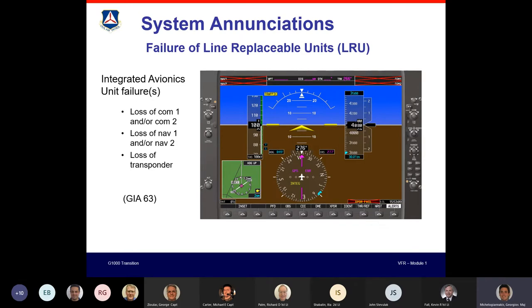Now, there's some training videos about it. If your AHRS is going to fail, the G1000 doesn't necessarily know that right away. So there is a period of time where you might get weird indications. So that's why we tell you to cross-check. We use standby instruments every now and then, especially if you suspect something is wrong, like if you get conflicting indications, like your airspeed is increasing where the nose is illustrated to be high.